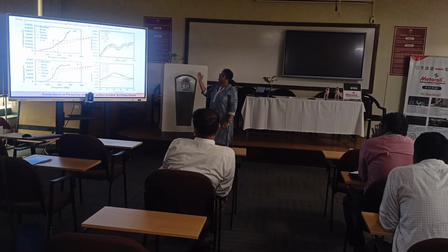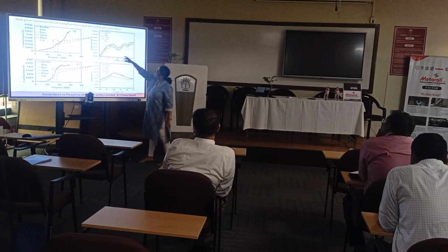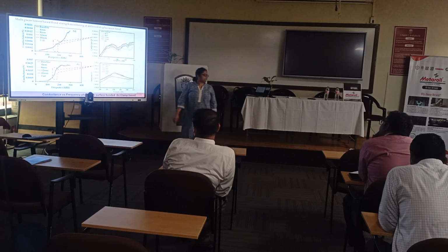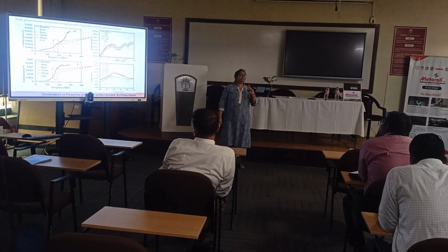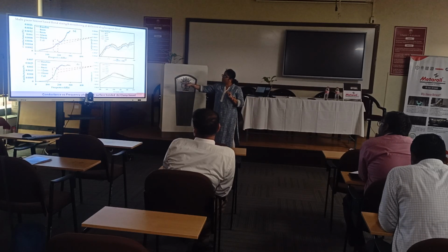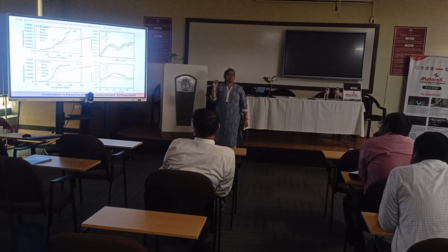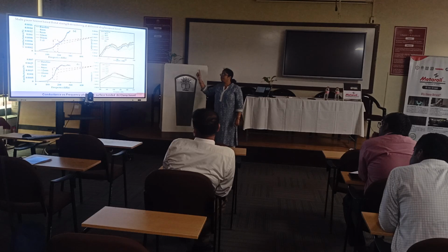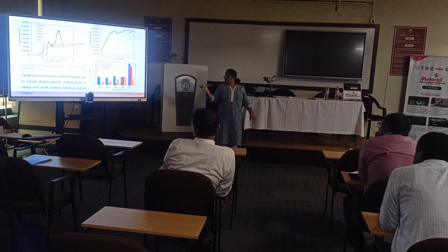But failure is shifting left. If you see failure, this one is shifting left, which is a change in frequency, a lowering of the frequency, indicating lowering of stiffness, which indicates the damage, the final failure. This is quite visible in the first two figures. The dotted one is shifting left, others are shifting a bit right, because there are local failures, but the final failure is global. For 4 mm, 8 mm, 12 mm, those strain control changes while we do the test are shifting right. This is the overall RMSD variation.